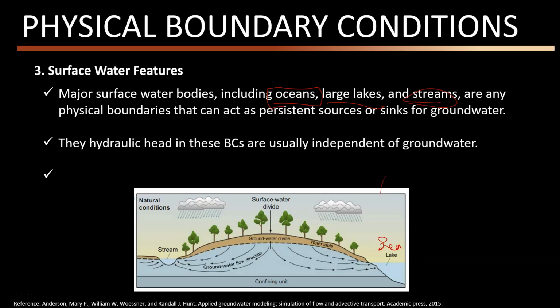We would like to extend our groundwater model to reach these spaces, because usually we have enough information about what's going on hydraulically, specifically the stage of the stream or the sea level, and we know that it is usually independent of the smallest and slowest hydraulic responses of the groundwater system.